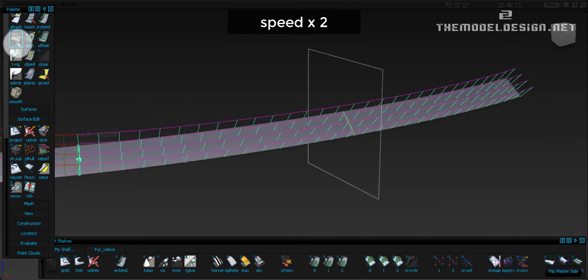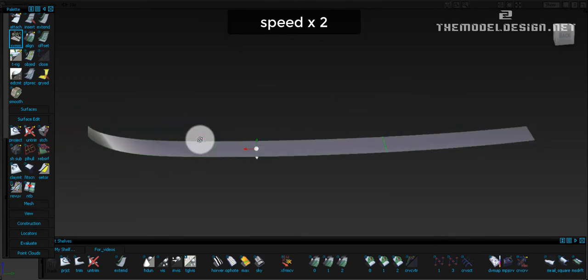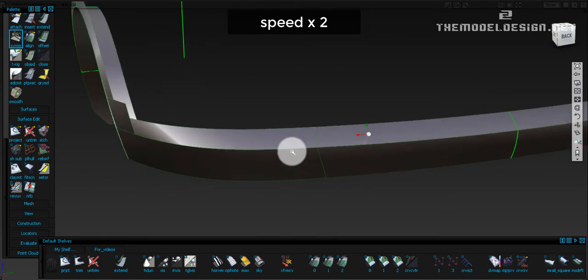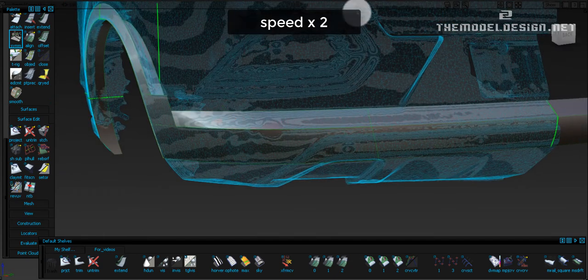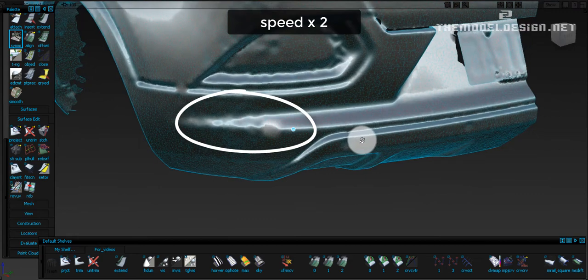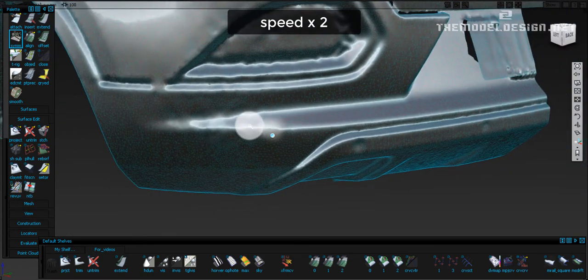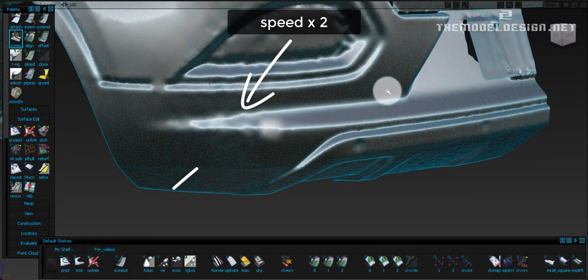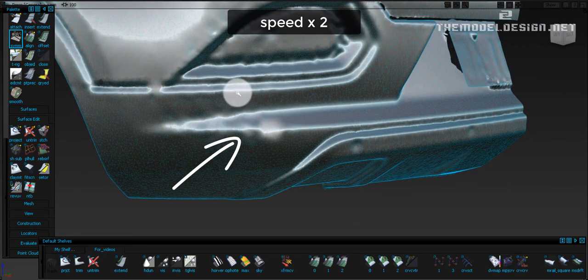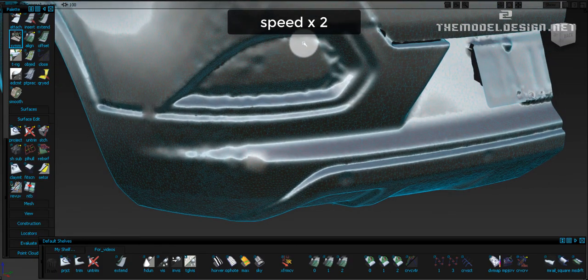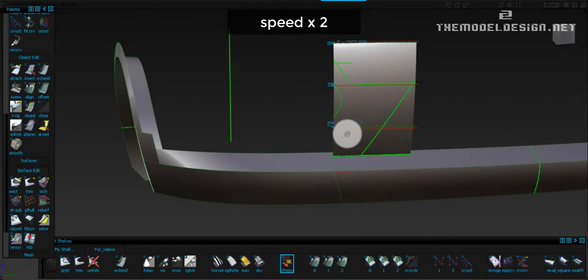In this particular situation, it's very important to have a good, consistent theoretical intersection. As you see, there is a lot of wobbling going on in the scan. Building surfaces around this corner was tricky not because of technicalities of the surface, but because of the scan's low quality. I wasn't sure where the theoreticals were located. In the automotive industry, it is pretty normal though that you often work to scanned clay data, which is not accurate at all, and you have to work out the right approach.